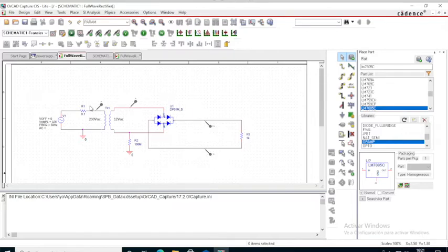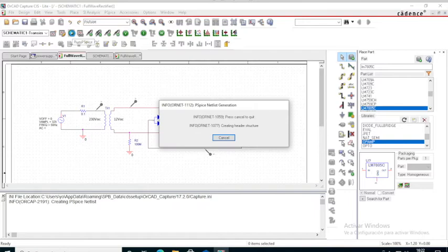So now we're going to simulate this circuit, and for that we put 2 voltage markers here in the input and output of the transformer, and a differential marker because here the ground is adjusting only in this part of the circuit. So here we have to put that differential marker to know how the signal is in the output. Okay, so now we're going to simulate it, running it.